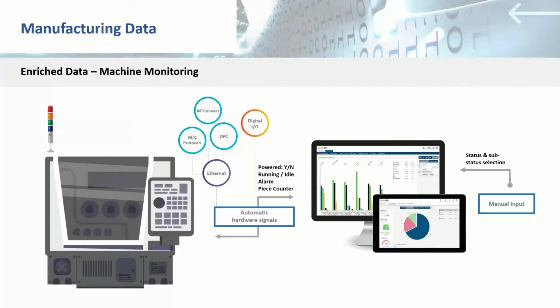Lamp stacks are a good thing to use in conjunction with the monitoring, as they can provide a visual status straight away, although there are screens that can display this as well. But you can see the status of the resource from maybe a distance. They're also a good place to obtain signals when you want to use the hardware monitoring. So the green lamp, the red lamps, things like this to pick up the alarm and the in production type signals.